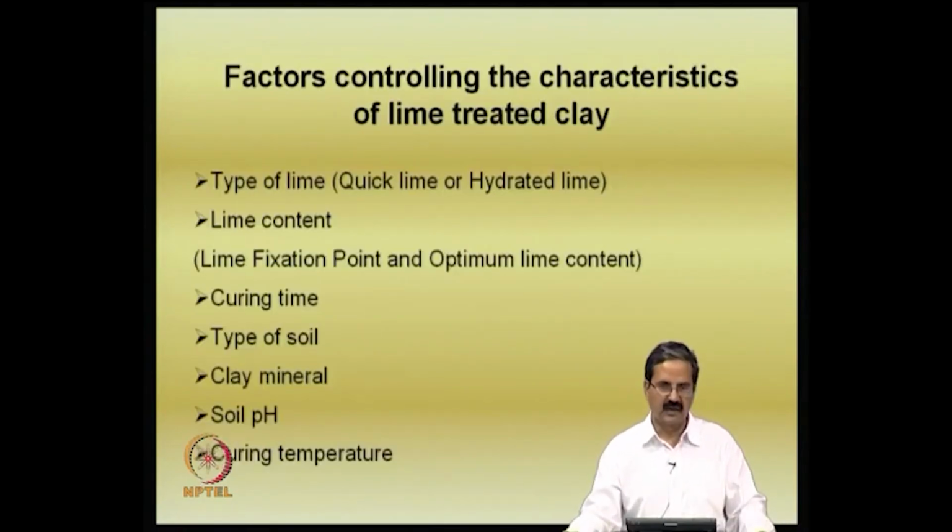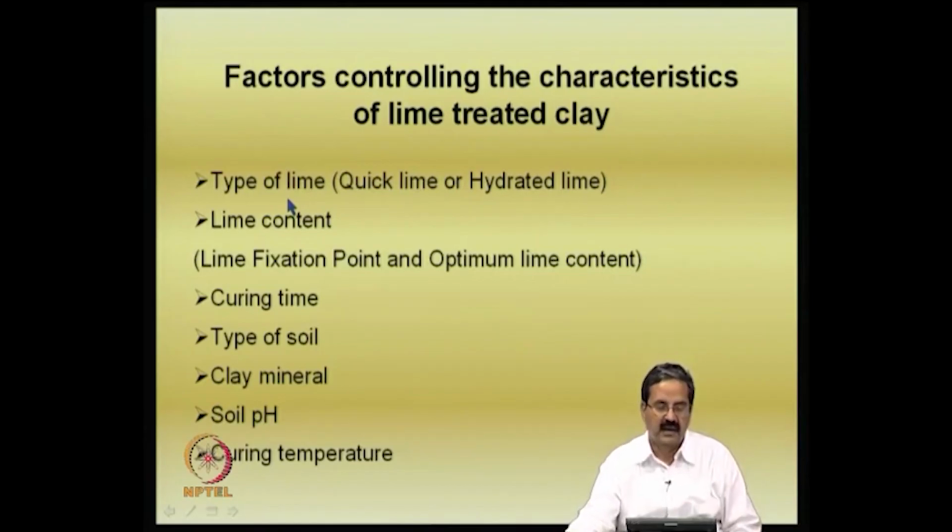And what are the factors that influence the characteristics of the lime treated clay? One should be able to understand the characteristics of the lime treated clay, and one is the type of lime, whether it is quicklime or hydrated lime, the content, like what percentage you are trying to add, and the curing time.